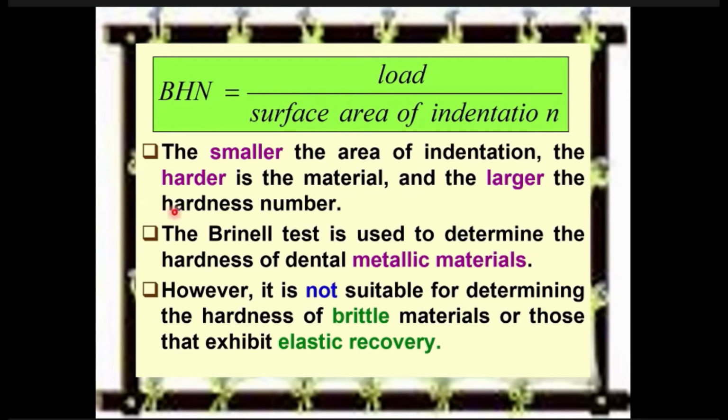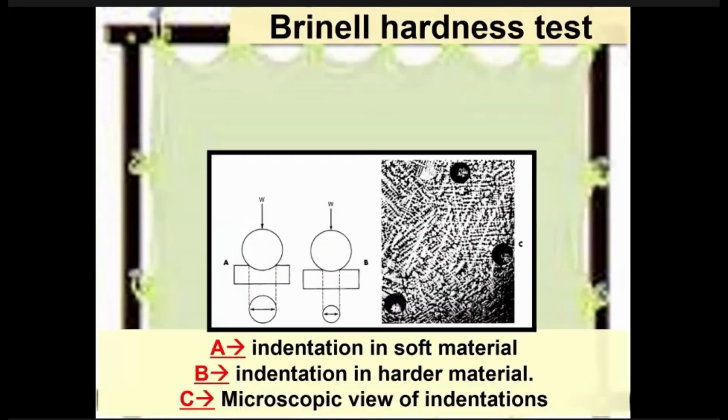If the indentation is smaller, the material is hard. If the indentation is large, the material is soft. So this will apply on all the methods. The problem with this method is the ball size is very big.